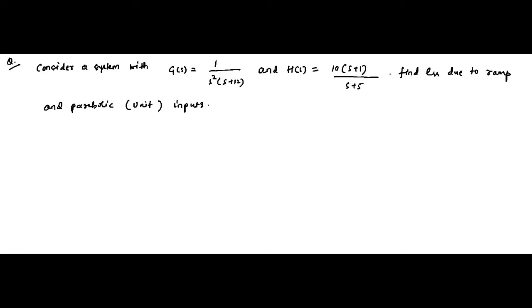Okay, so again, before dealing with such systems, first we have to write out the error equations for non-unity type feedback systems. That is given by Kh E(s) = R(s) - Kh C(s), where C(s) is the output, R(s) is the input, E(s) is the error signal, all expressed in the s domain, Laplace transform of the time domain signals.